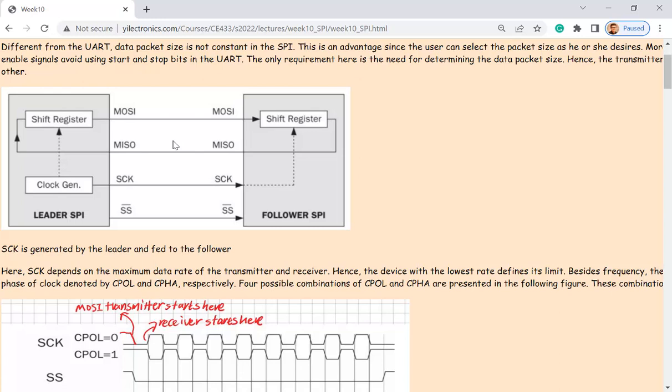But actually, it's just one of the four modules. It is a transmitter for the slave or the follower to be implemented in the sensor. You don't need two of them. You just need one. You just need the transmitter for the follower. Okay. So the 8-bit parallel data will be converted into serial data in the SPI protocol and being sent out to a master, whatever you are using. A quick question here. Can you use Arduino to interface with this sensor? Can you use Arduino to interface with it?